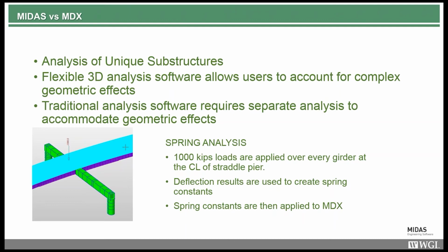For the shears, what you'll see here is that we have, once again, very, very good correlation between the two models, which is very good in terms of giving everyone the confidence that MIDAS Civil is capable of handling this kind of analysis. Just don't worry about the slight offset between these two lines. This was created simply because I grabbed the J node during all of my analysis. If I had selected the I node, we'd have a true vertical line here as well.